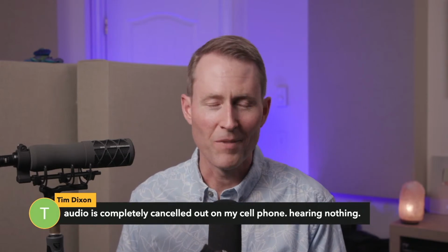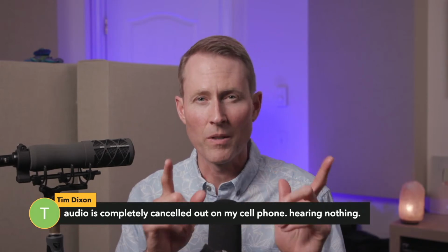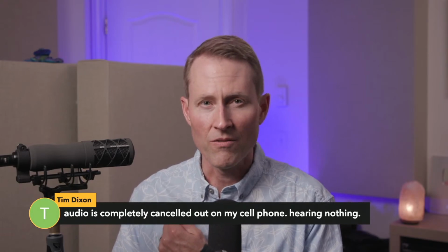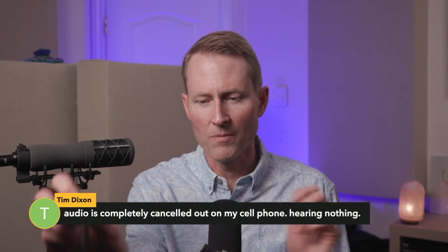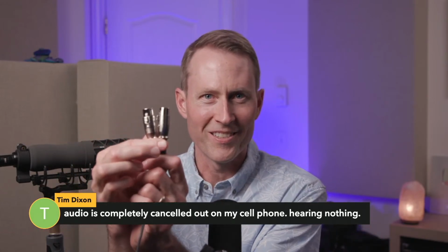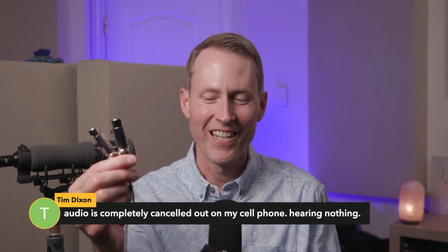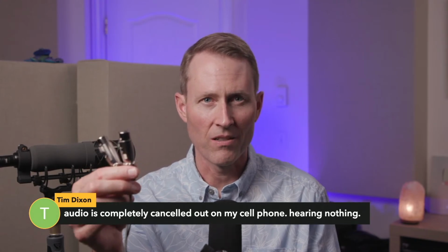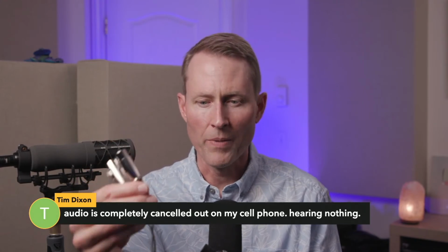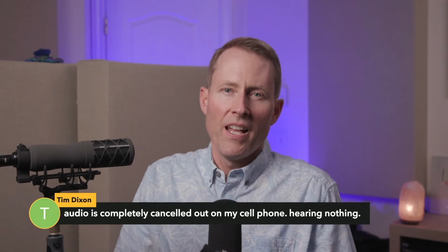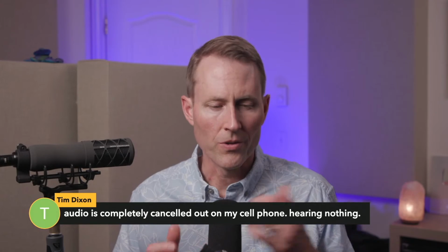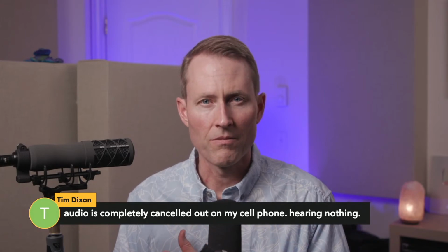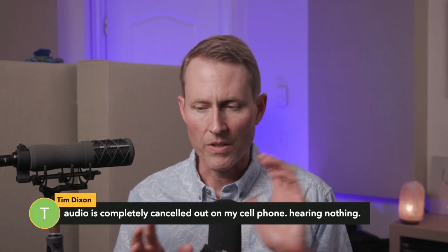And when they do that, they cancel out each other exactly when we were using the phase inverted audio sample earlier on, when I used this bad cable. I'm going to call it the bad cable, that was not converting to unbalanced, but actually just sending all three poles of the balanced connection. So that's exactly what the problem will be if you're not careful and you don't work through sending the right type of audio from one piece of gear to another.